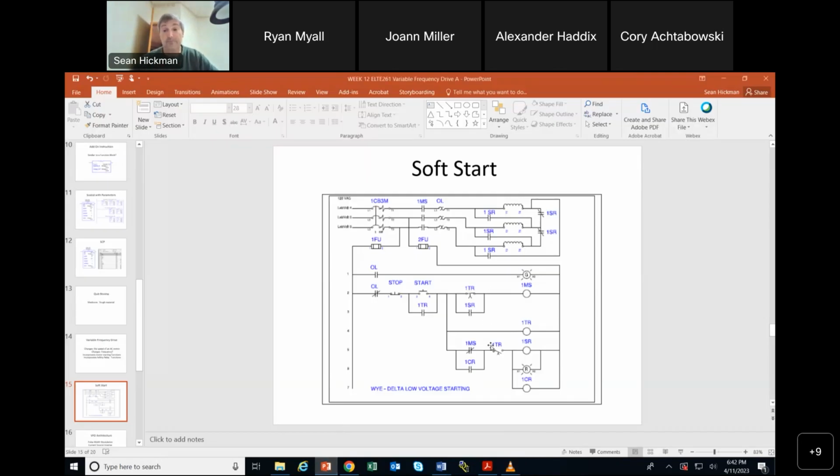Now this circuit here is what you built in 232. We got a lot of problems with it. You're in a race here because you got an SR contact here that's closed and an SR contact here that's open, and an SR relay here. So when this relay hits, these close and this opens. Well, you definitely want to be sure that these open before these close.